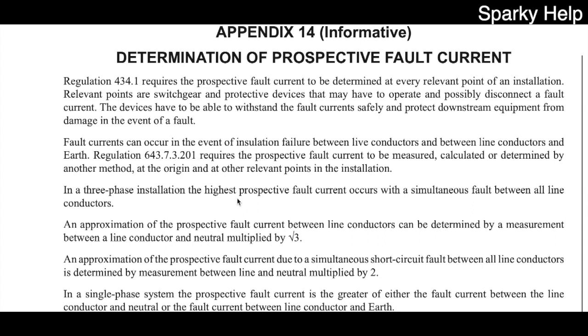Well, you could put your meter across it. However, I would read the instructions before doing that, just in case your meter cannot do it, and it will actually destroy your meter. So please read the instructions before putting your fault-free impedance tester across a couple of phases.